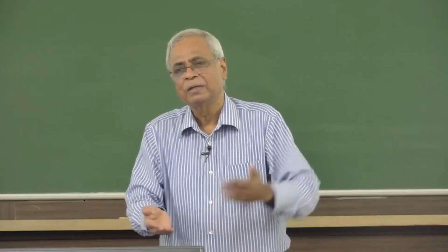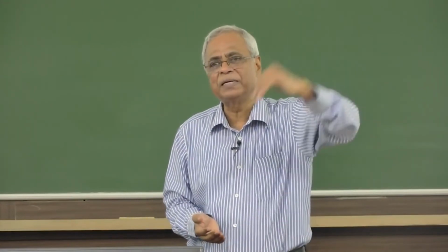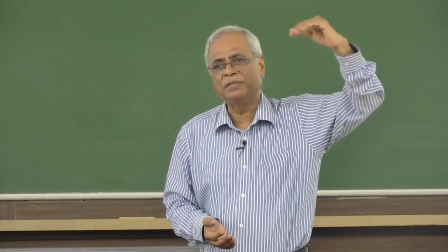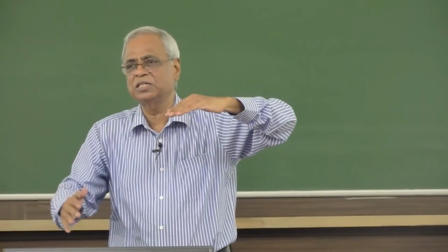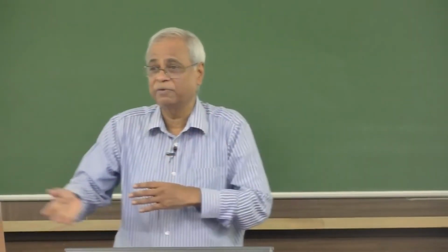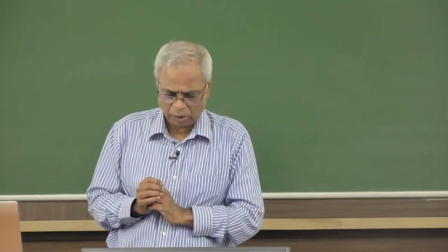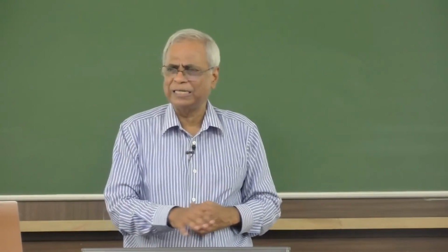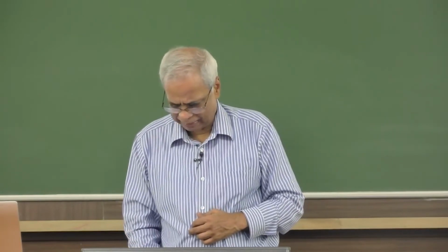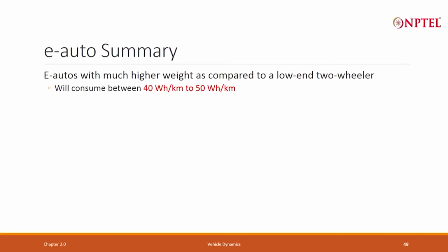So, what is regeneration? Deceleration, kinetic energy is getting converted to electricity. What about climbing up and down? When you climb down, you have gravitational energy, the potential energy, you are converting it back to electricity. So, that is what you will do. I think getting 40 is quite easy, and that is what people are getting. So, e-auto will consume between 40 watt-hour to 50 watt-hour per kilometer.